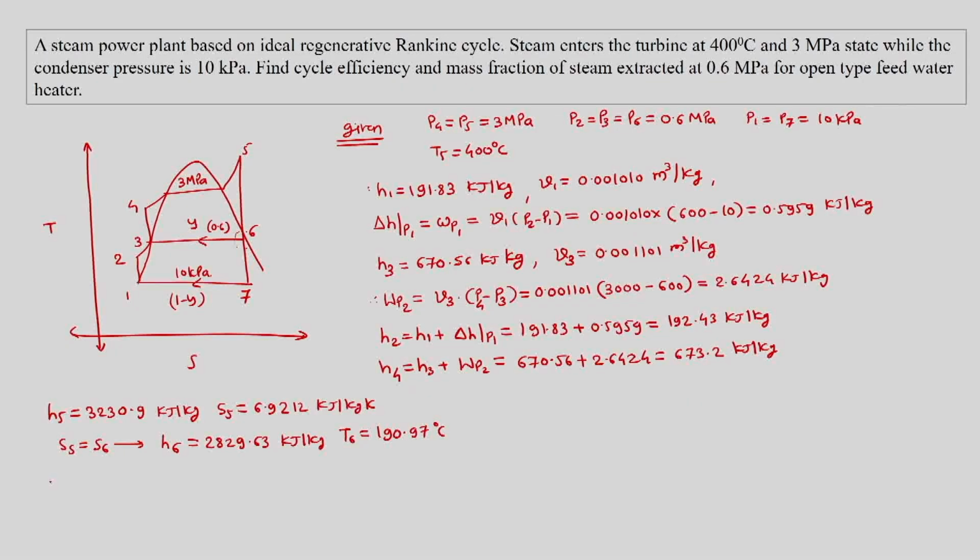Then we have everything necessary to find the mass fraction. We can directly use the formula y is equal to H3 minus H2 divided by H6 minus H2.